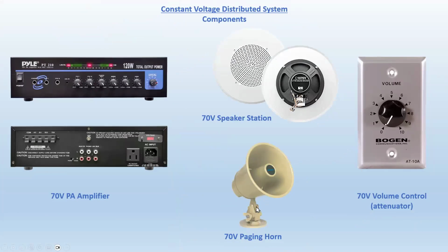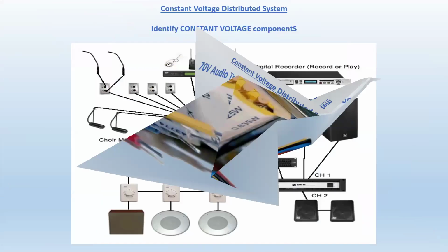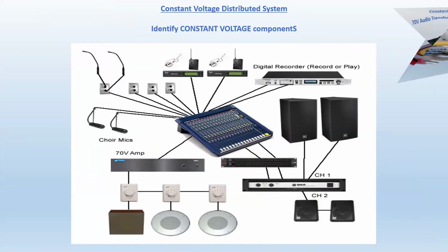And here's a paging horn. At the other side of that, it just has 2 connections, and there's a screw terminal. So with a slotted screwdriver, you just tap into which wattage you want to set that to. That's what the transformer looks like. We just talked about that.